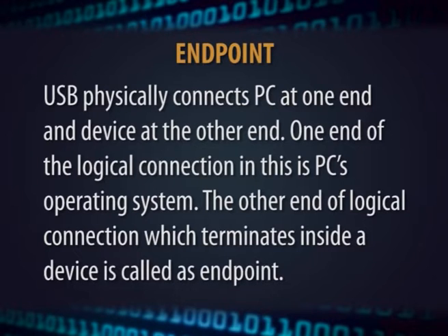Endpoint. USB physically connects PC at one end and device at the other end. One end of the logical connection in this is a PC's operating system. The other end of logical connection, which terminates inside a device, is called as endpoint. The endpoint is a source or destination of data being exchanged with PC. Each endpoint in a device creates a unique logical connection with OS.